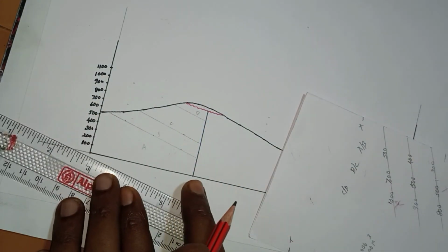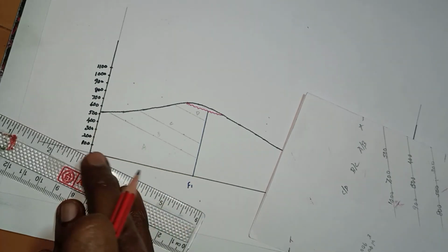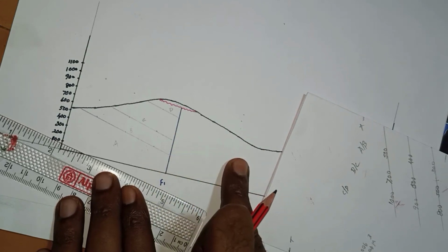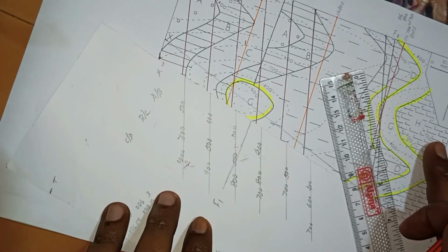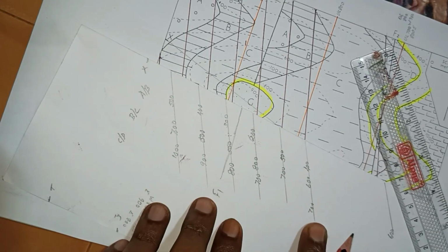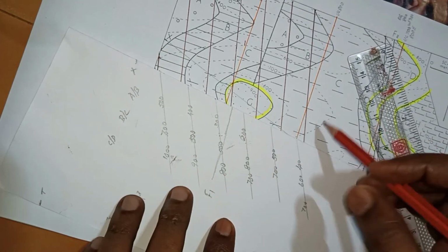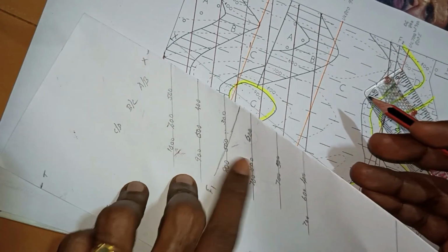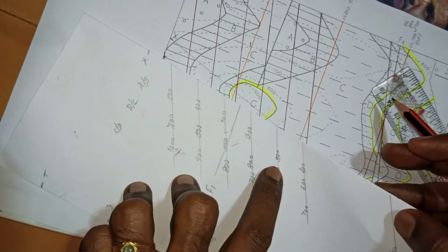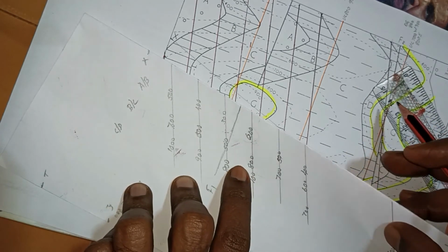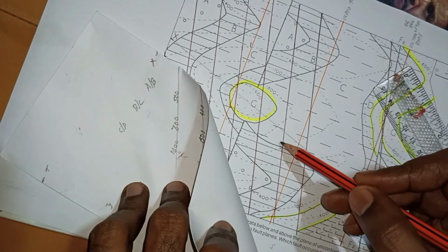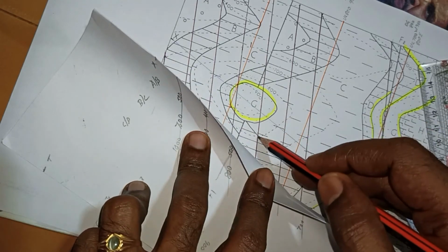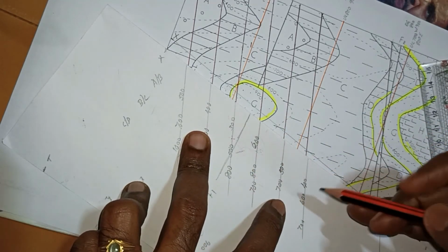So now the beds between the fault and the west direction are plotted. Now we will draw the east of this fault F1. The values are plotted here. The AB boundary is 600. You can see the bed is dipping here. Downward it is decreasing, so 500 and 400. Next is the BC boundary. Here you can see the BC boundary. This is 800, next 700 and 600.